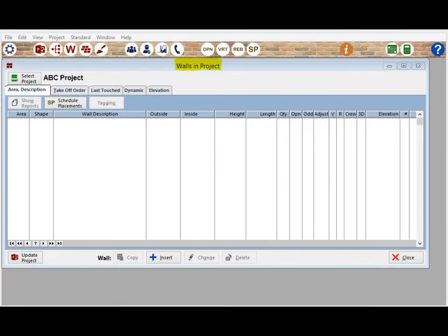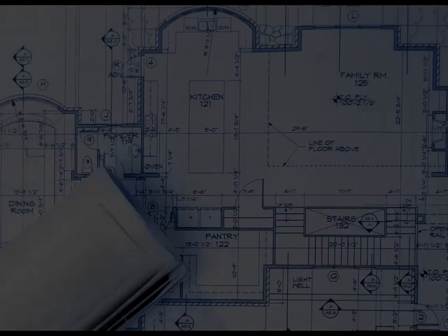You are going to continue your project by creating 4 small walls: north, south, east, and west. Some of the walls are going to be 10 by 10 or 100 square feet. There are 6.752 brick units per square foot. This wall would then have 675 brick. Simple walls with simple calculations that you can do in your head so that you may come to understand how the program works. Let us get started.